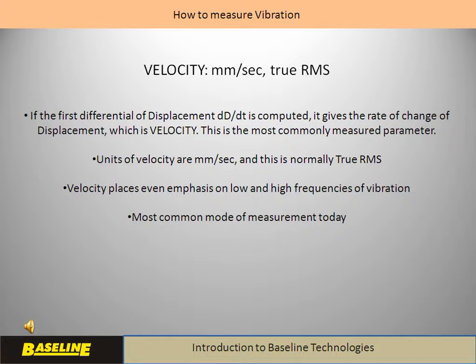Velocity factors in both displacement as well as frequency. The metric units of velocity are millimeters per second. Velocity places even emphasis on low and high frequencies of vibration.